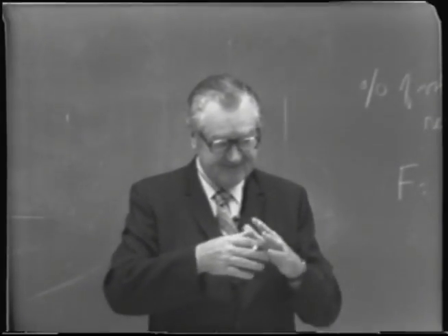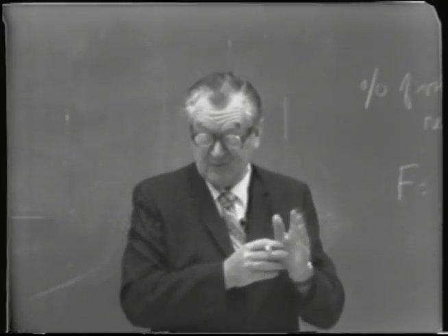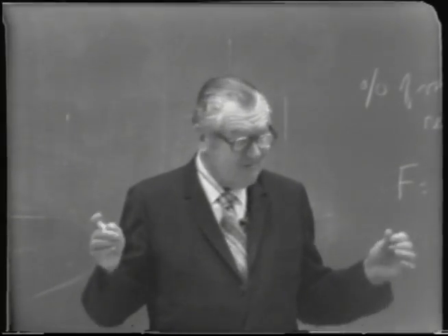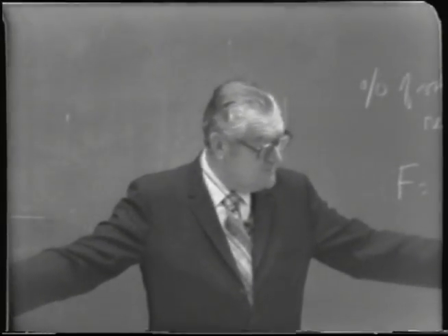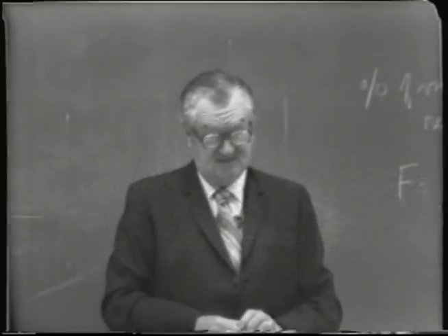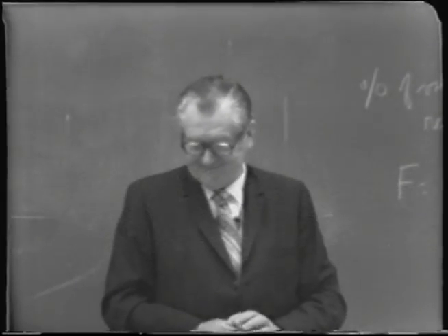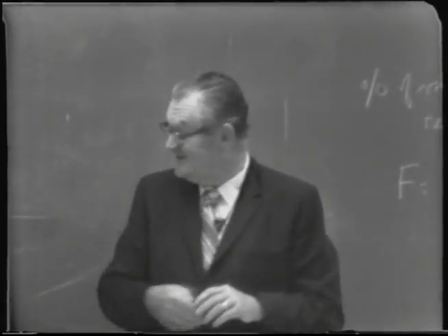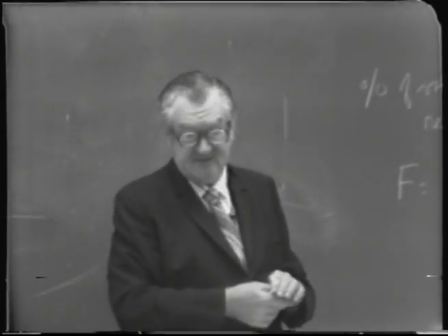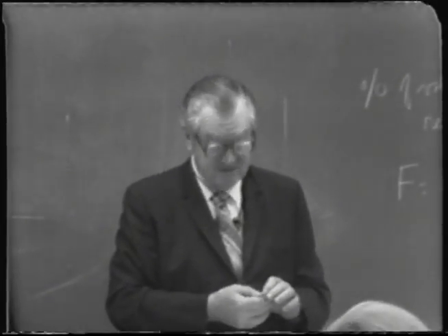The required cross-sectional diameter is directly related to the amount of the vapor load. So naturally, for a bigger distillation quantity, you have to have a bigger diameter. Not necessarily a bigger height, but it's going to be a bigger diameter.